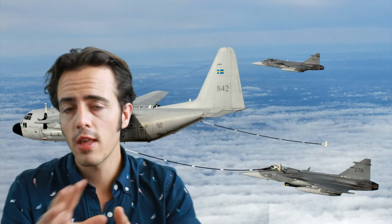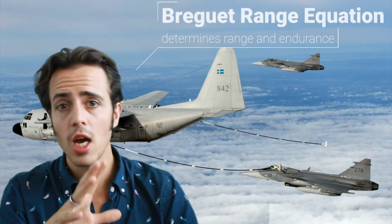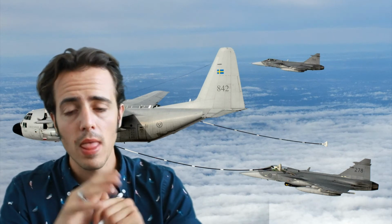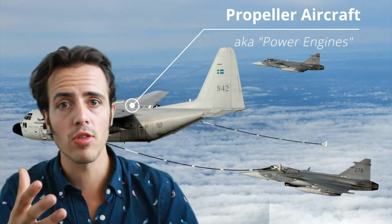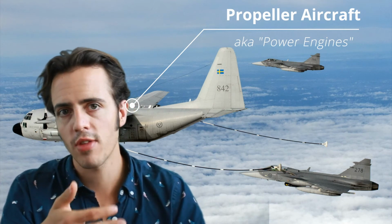The way that we calculate these two quantities is by developing something called the Breguet range equation. And we calculate it slightly differently for the two broad classes of aircraft that we've already spoken about. So we spoke about propeller-driven aircraft as being power engines. And we spoke about pure turbojets as being thrust engines.